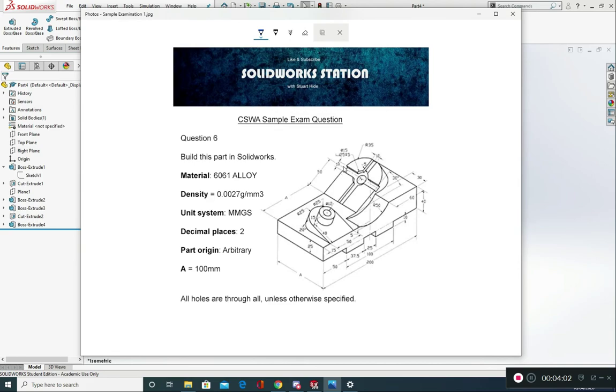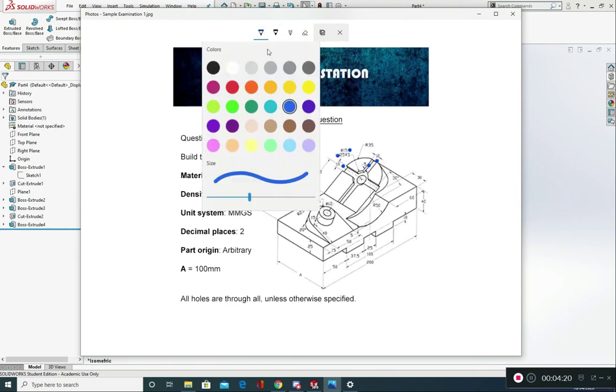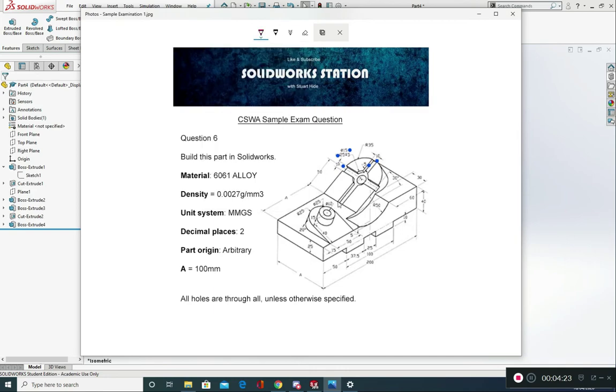We've got a 10mm width to this channel, a 10mm width to this channel that we've got running from top to bottom. We've got a 5mm cut that's happening, a 15mm hole in the center, and a 25mm circle around the outside. We also are going to highlight some stuff in red that might cause issues. This point here, I am guessing that we might need to move a face here, as I think that's going to come back at a 30-degree angle as opposed to 90 degrees.